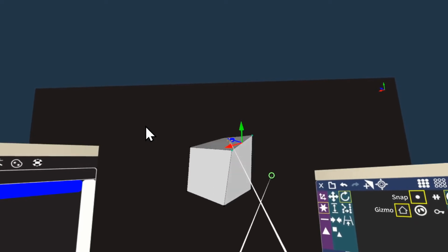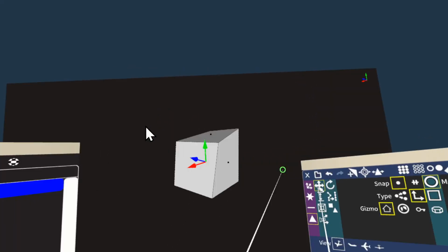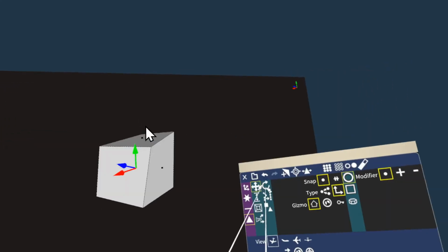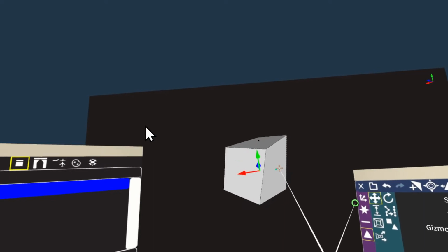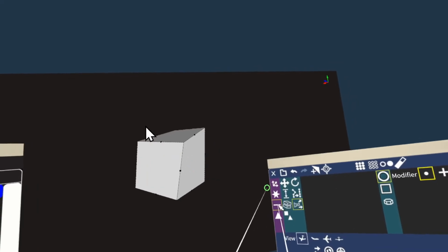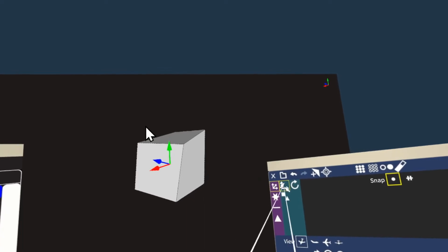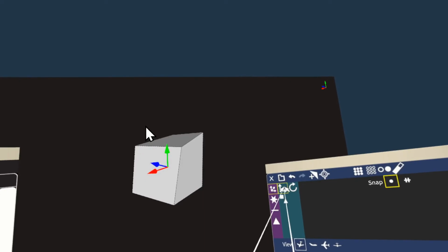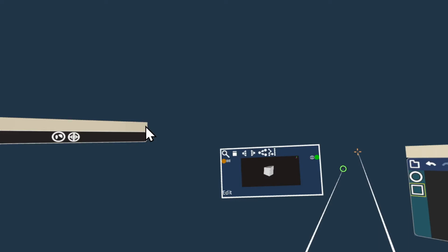The Faces component also has a Rotate and a Move tool, just like the vertices, and they are used in a similar manner. Just drag on the Faces point, the dot in the middle, and drag. The Edges component also works in a similar manner. The Transform component has a Rotate and Move tool as well, though they can only be changed with a gizmo. Now I'll go back to the network view. To do this, I tap on the Exit Cross button.